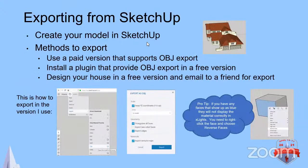And on this next screen here, you'll be able to go back. Hopefully I'll get this presentation out to the guys where they can provide it, and you can go back and reference this. If you are using SketchUp, I show here the menus that you can use to get down and export as an OBJ. I've also got some tips here on the options you want to use.